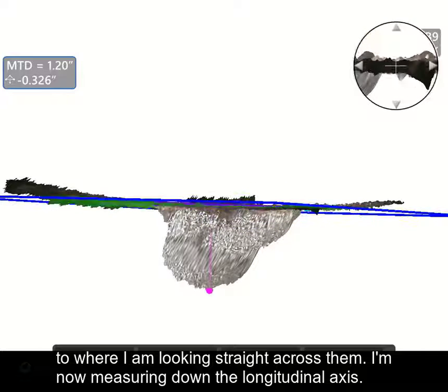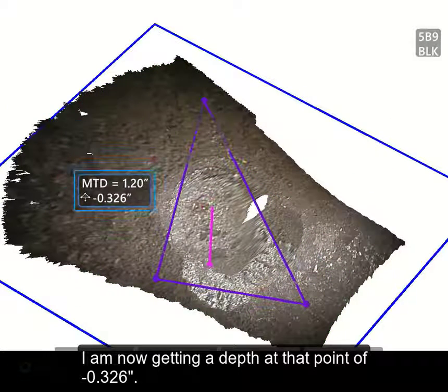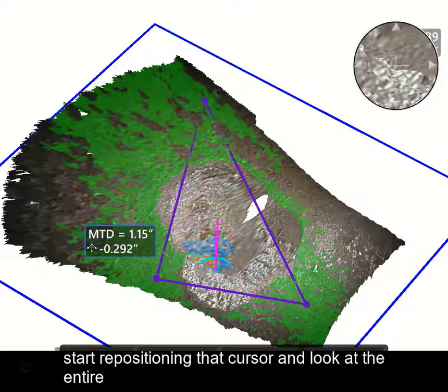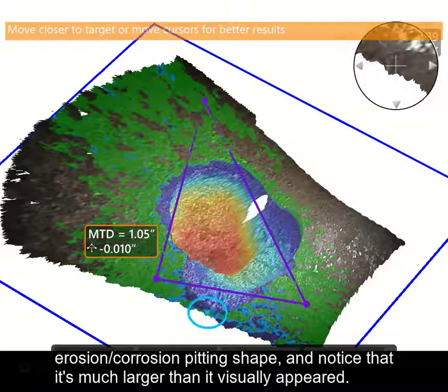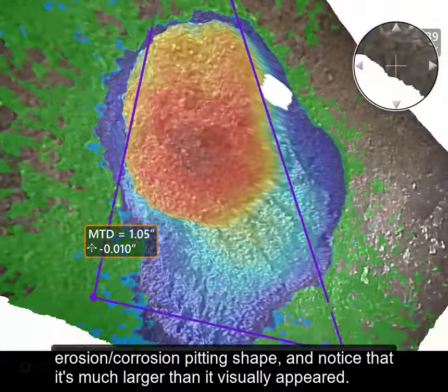I'm now measuring down the longitudinal axis. I'm now getting a depth at that point of 326 thousandths. I can then, with an additional surface mask in Real3D, start repositioning that cursor and look at the entire erosion, corrosion, pitting shape and notice that it's much larger than it visually appeared.